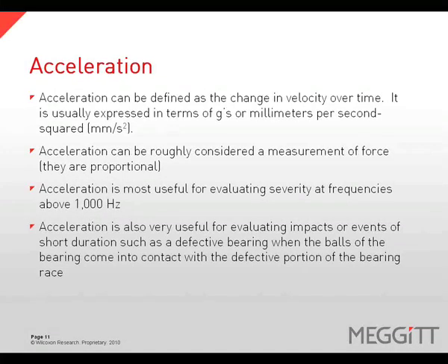Acceleration can be defined as the change in velocity over time. It is usually expressed in terms of g's. Acceleration can be roughly considered a measurement of force. Acceleration is most useful in evaluating severity at frequencies above 1 kHz. Acceleration is also very useful in evaluating impacts or events of short duration, such as a defective bearing when the balls of the bearing come into contact with the defective portion of the bearing race.